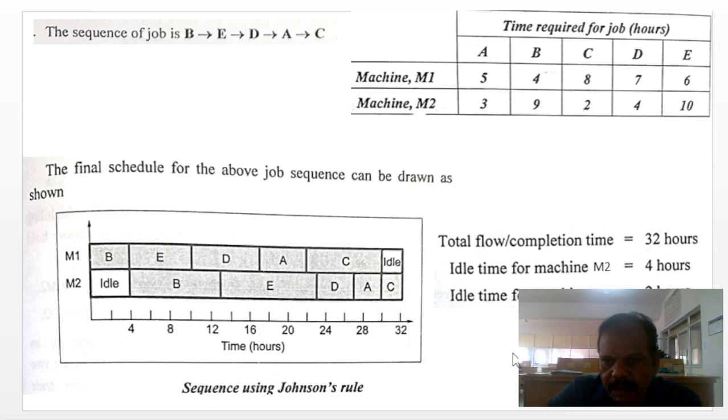This is called production scheduling, and also production sequencing. The orders are sequenced in such a manner that the flow time or the total work time will be minimum. We use Johnson's rule here for getting the optimum sequencing time, and by calculating the idle times for each machine.